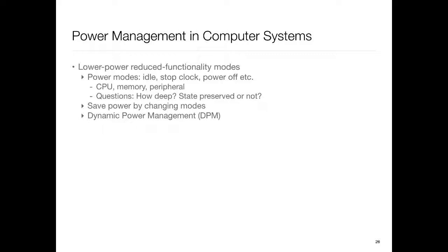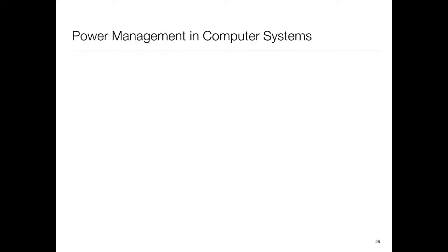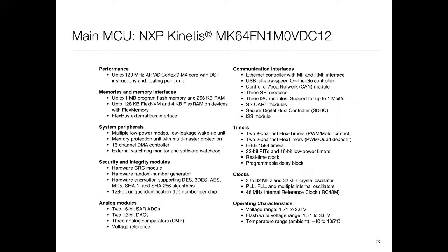Also, when you power off and then restart, it's not as if I command the power supply to turn on and immediately the voltage goes up. The voltage going up takes time, and it takes time for the clocks to come up. That could be in milliseconds. So depending upon things, going into a deeper state may not be very effective, and you might want to go into a shallower state. Usually processors or MCUs provide a whole bunch of power management states. Let me see if I had something out here.